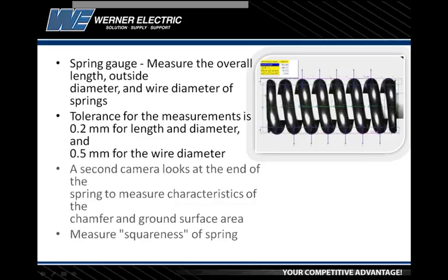Here's another gauging application, measuring a spring. So measuring the overall length, the outside diameter, and even the individual wire diameters as it's wrapped onto this, whatever that rod is in the middle that's holding it. A second camera isn't shown. The image is only showing one image, but there's also a second camera that looks down the end of the spring at this chamfer.